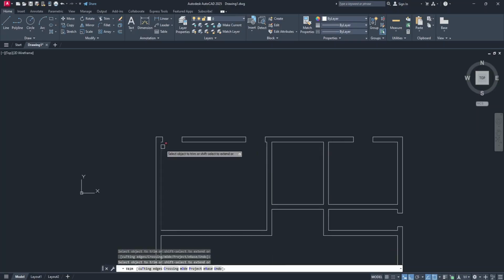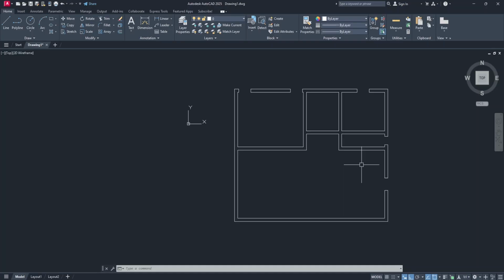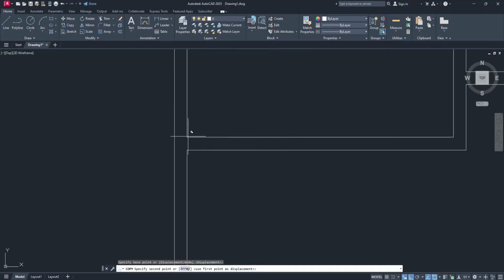And now we have our two openings, and for the ones here, let's copy a vertical opening of 900, which is this one. Select this line and this line, click on copy, select this endpoint and click here, press the escape key, select this line and this line, click on move, click once, point up. Now type 450 and press enter.